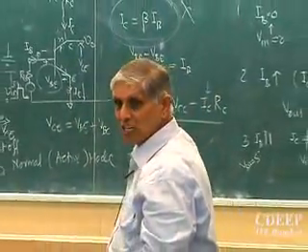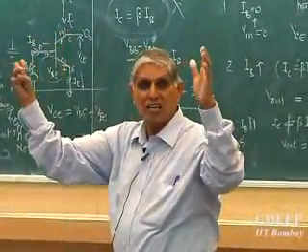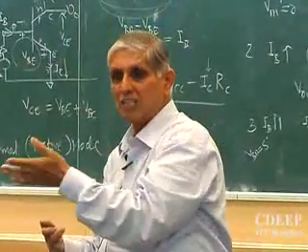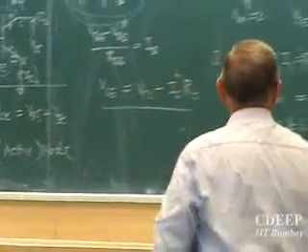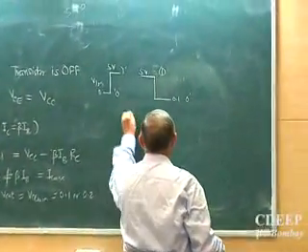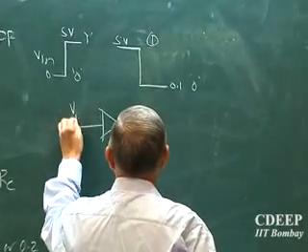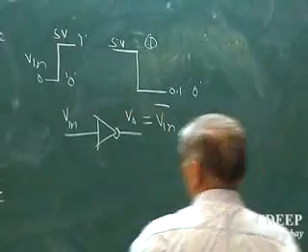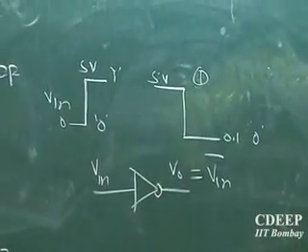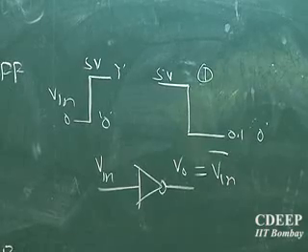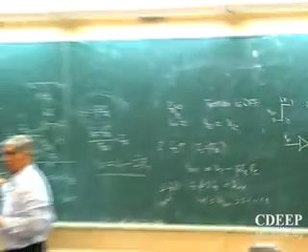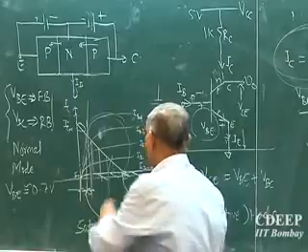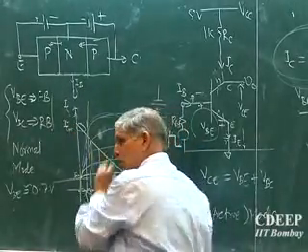This theory which you got here was derived from understanding of a bipolar device, and from there I know that if I put such an input, I'll get such an output. So I can now use this as an inverter. The inverter symbol we know is something like this, V in, V out, and that is always equal to V in bar. This is an essential feature of a bipolar transistor, that we operate in 3 modes: cutoff mode, active mode and saturation mode. In a digital circuit, I will switch to cutoff.